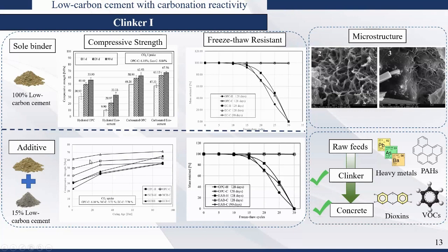And we do have the luxury to do carbonation, because for carbonation, we need a carbonation chamber and pure CO2. So it involves some capital cost, and we know that not everybody has the luxury of a carbonation chamber. But if we do, this blended cement achieves the highest strength compared to other batches. The freeze-thaw resistance test shows similar results: if we do carbonation using our material, it can achieve very high freeze-thaw resistance compared to our reference batches.